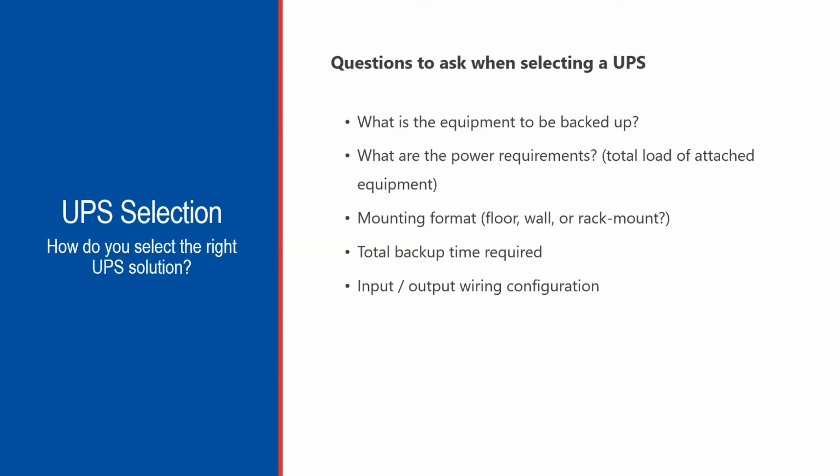Last but certainly not least, the input-output wiring configuration. Like a mounting format, UPSs are available in a variety of wiring configurations. Asking this up front can eliminate problems down the road. I think that this is probably one of the important questions to ask, because more often than not, we've seen it in the field when they've received a UPS solution and realize that they don't have the right input plug. Understanding the input and output wiring at the facility, at a data center, in a security closet, an IT closet, whatever the application or the environment will be, is crucial and key.